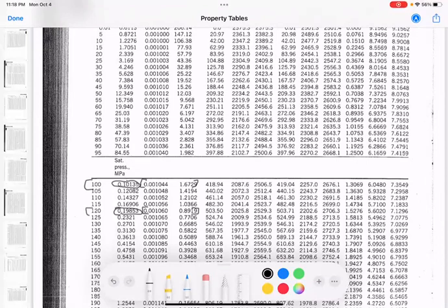Because we're at 0.85, we're getting really close, so we have a very high quality mixture, but we're still a mixture, so we're okay to keep using this. And it means that the pressure at 120 degrees Celsius is 0.19853 megapascals, so almost 2 atmospheres.